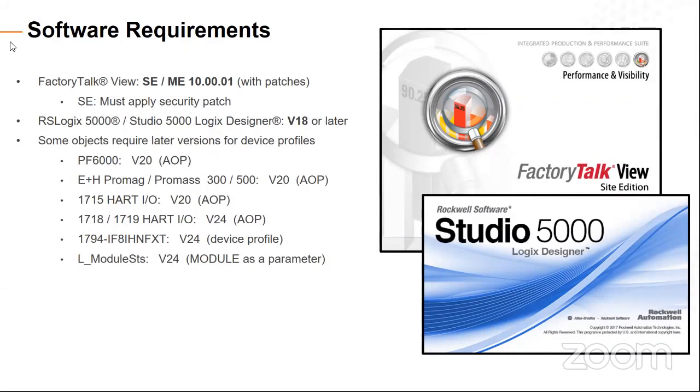For the limit there, the SE version 10, we're looking at the process library object, the new set. So that horizontal grayscale when we came out with the 4.0, the minimum version that you can be on there is 10. If you are still running FactoryTalk View version 8, version 9, you can use the older file set of the library. So the 3.5 library set that we had is still available on the process download site. So the PCDC, you can go in there, just type in process library, and it'll give you, just like any firmware, the options of what library to download.